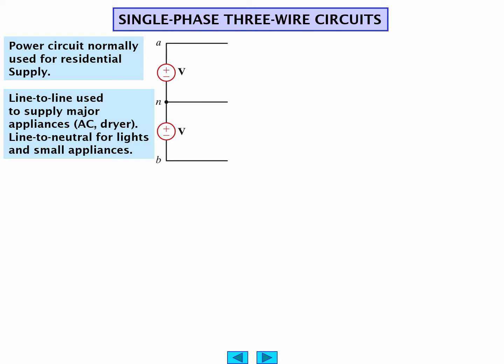We're going to talk a little bit about AC and how it's used in household electricity. But also this is industrial. Well, it's close to industrial, not quite. This is normally how household electricity works. This is 120 volts at 60 hertz, and that's in the USA. And they're 180 degrees out of phase.